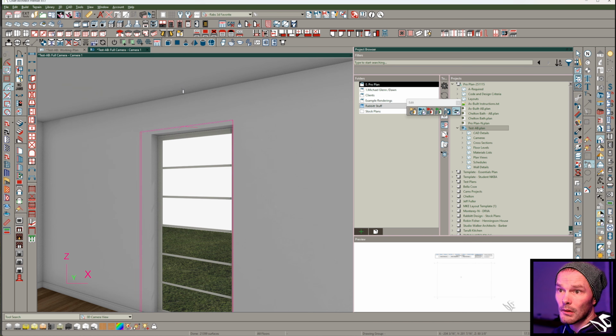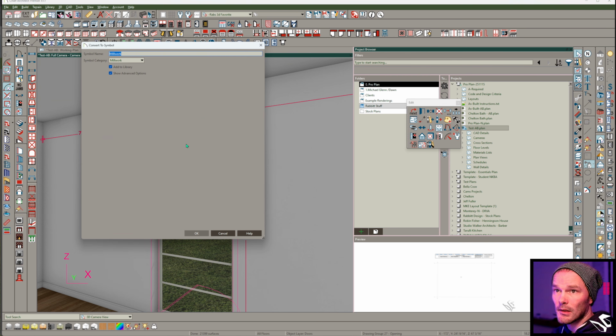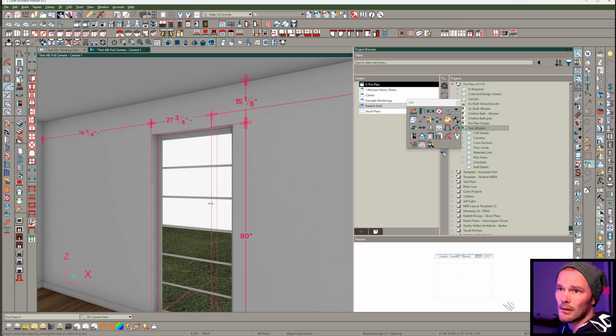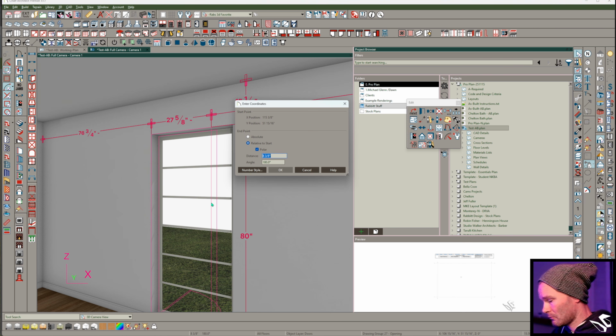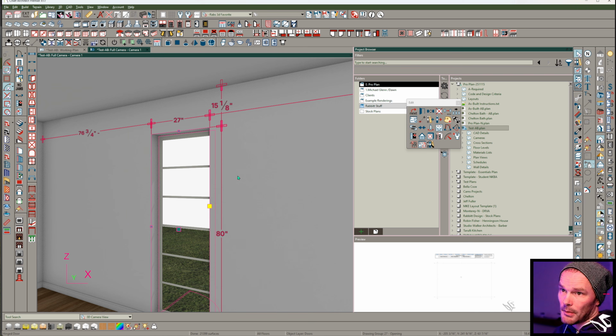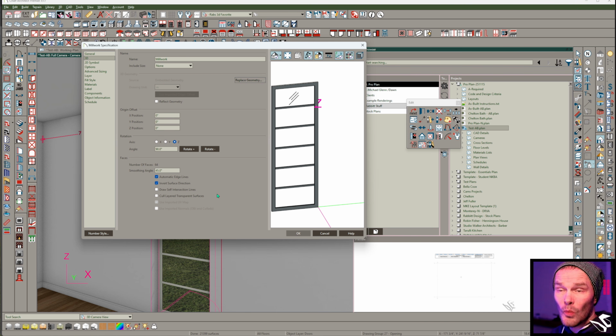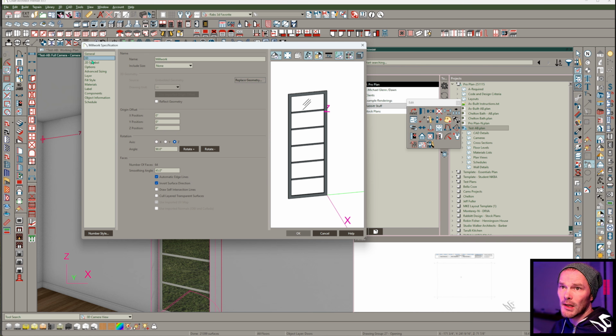Oops. Oh, escape. Big mistake. Don't hit escape. I guess I could have made this the right size right here. Let's just make this 27. Selected to symbol, millwork, show advanced options, 3D. We know we're rotating it 90. And you might want to set some stretch planes, up to you. Stretch planes will make it so that we're not interrupting the stiles and rails here. Those wouldn't get resized as it gets applied to different cabinet sizes.